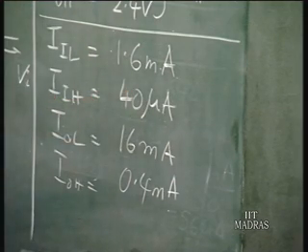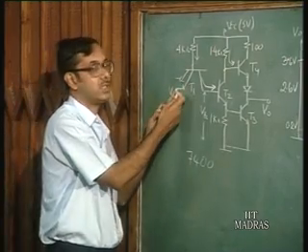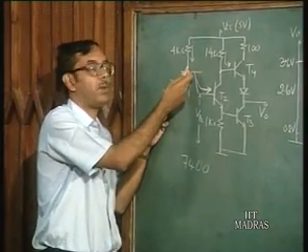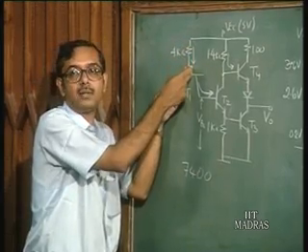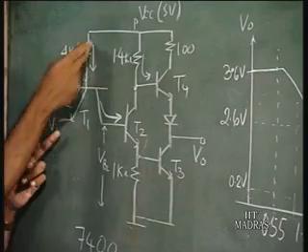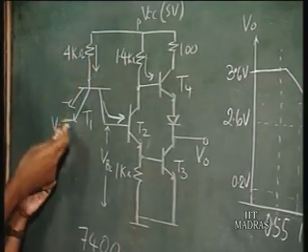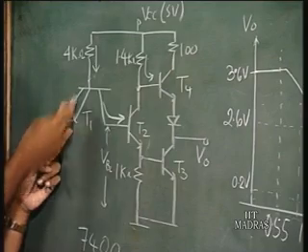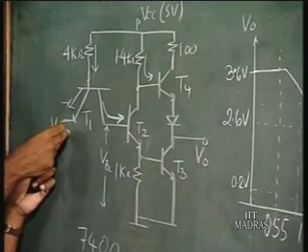So, obviously, you will see that if you go back to this circuit here, when input is low, say 0.2 volts, this would be 0.9 volts, which would mean actually a current of 1 milliampere. Since this transistor's collector current is almost 0, the base current is almost equal to the emitter current. So, a current would flow in this way equal to slightly greater than 1 milliampere.